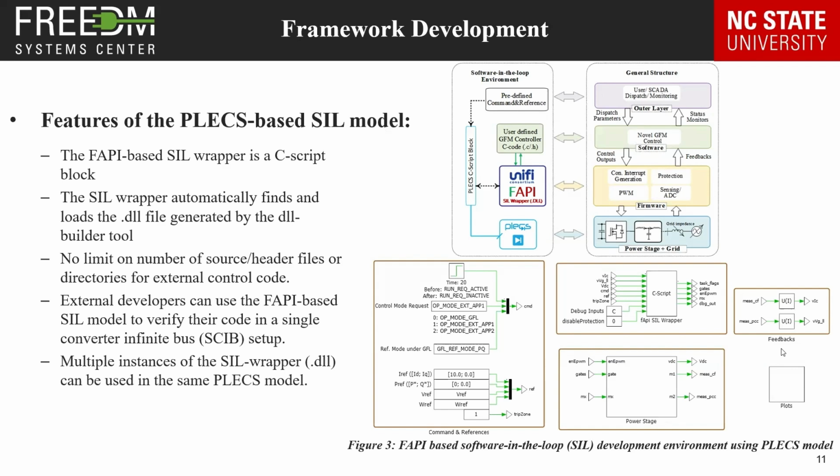It also accepts reference commands and passes them to the software layer, which is designed to accommodate user-defined grid-forming models. In the Plexim-based SIL model, FAPI is included as a single dynamic link library, and external control software can be included as white box with as many header and source files as the user desires. The FAPI-based SIL model can be used by an external developer to verify their code in a single converter infinite bus setup. Multiple instances of the SIL wrapper can be used in the same Plexim model.